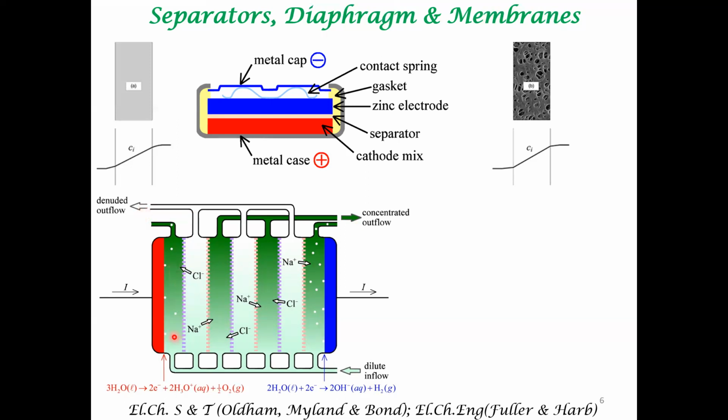So it is again an electrochemical unit. There are electrochemical reactions, in this case hydrogen evolution on this electrode, and on this electrode oxygen evolution. Okay, so when oxygen evolution occurs, there is, let's say, proton generation. In this case, you can imagine this compartment becomes more positively charged, and Cl minus from this compartment will get selectively transported across this membrane.